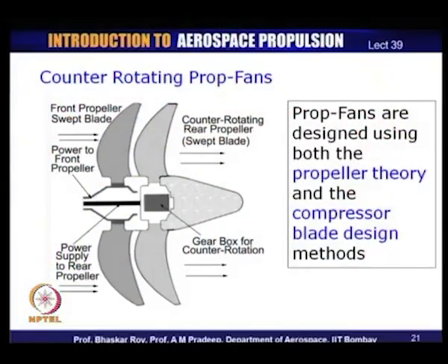They are extremely efficient devices, and as I said, indeed more efficient than the big fan engines that you see flying around today. It is simply a matter of time before these prop fans take over flying the big aircraft. One version of the prop fan that is again being developed very seriously is known as the counter rotating prop fan, and we had a glimpse of it once before. Let us take a closer look again.